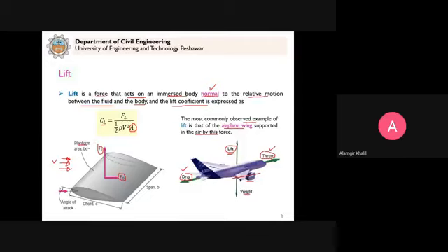What we mean by the planform area: if you look at this object, it has this span b, but on this side, you can see this is the curve. So what dimension should we use? We use this chord c. And if you look at this plane from the top, what will appear? It will appear as just this dimension multiplied by this dimension, the span.